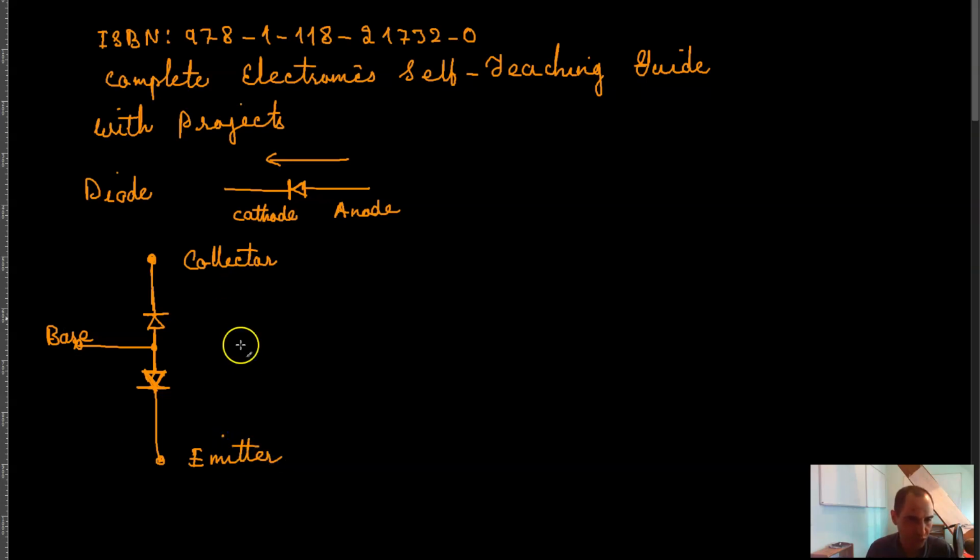Of course, it would not be a true transistor, but a device very similar to one, meaning that a transistor is basically nothing but two PN junctions connected together in this manner. And so this would be an NPN transistor. This would be the N-type material, this would be the P-type material, and this would be the N-type material. That means that the cathode is the N-type material.